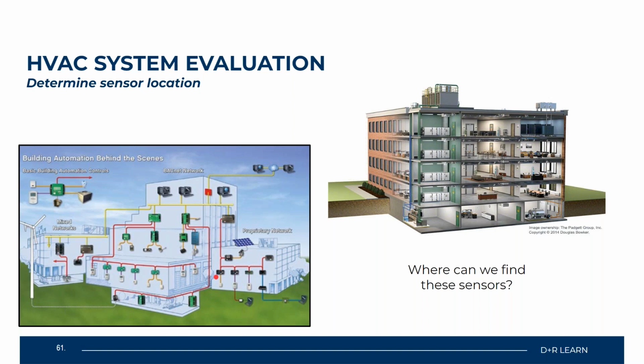So another place you can find these sensors is outside of the facility. Remember, we want to put an ambient temperature sensor out here somewhere on the top of our building, kind of hanging off the ledge, with some sort of shroud or cover to protect it from the elements. But what it'll be able to do is measure our temperatures at a decently high point with no obstruction. That way it can send that signal back to wherever the mainframe is located in this facility.